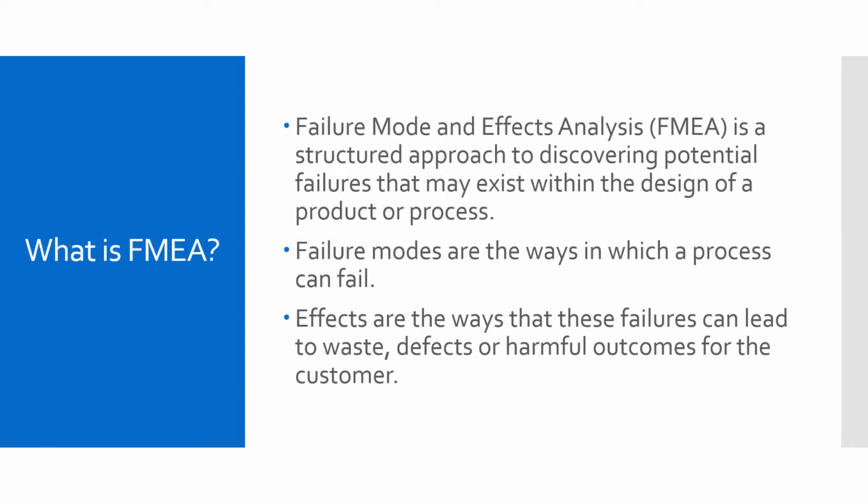Failure mode and effects analysis, FMEA, is a structured approach to discovering potential failures that may exist within the design of a product or process. Failure modes are the ways in which a process can fail. Effects are the ways that these failures can lead to waste, defects or harmful outcomes for the customer.